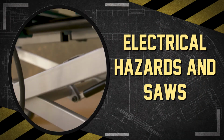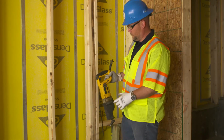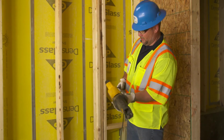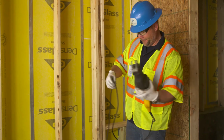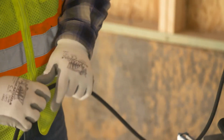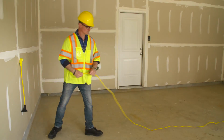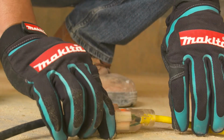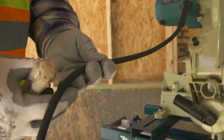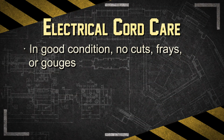Electricity is needed to power most saws seen on residential construction sites. Therefore, as with any power tools, saws have the potential to present an electrical hazard if not used and maintained properly. All electrically powered saws should be double insulated or be properly grounded with a ground pin at the plug. Cords to saws should be maintained in good condition and not contain any cuts, frays, or gouges to the outer jacket that would lead to exposed wiring.